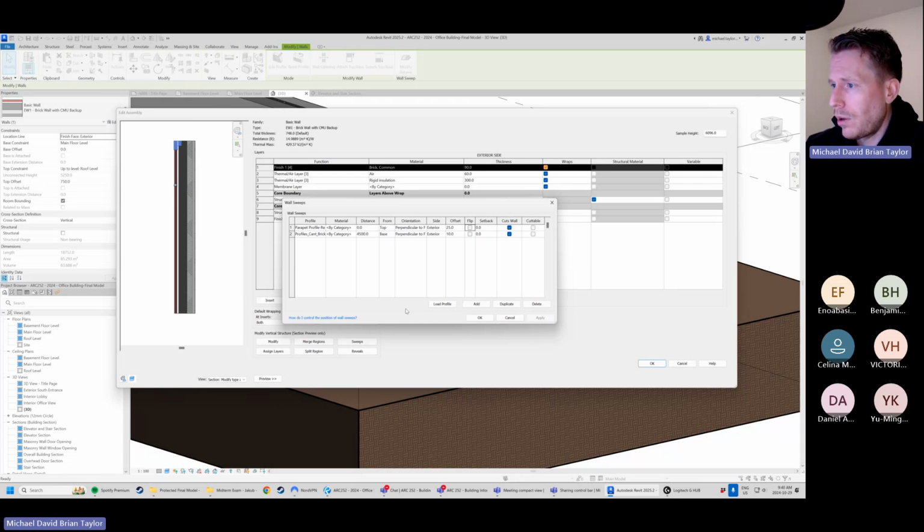So for us right now, I know the way that Jacob had done it in his tutorial, which I find a little bit tedious, but I'll show you how I would do it if we actually want that to face the other way. And if we do that, we're going to actually change this to the interior side, hit apply. You can see how it's literally flipped. And then you would actually offset it to the dimension of the wall, which is, I think, for us 748.